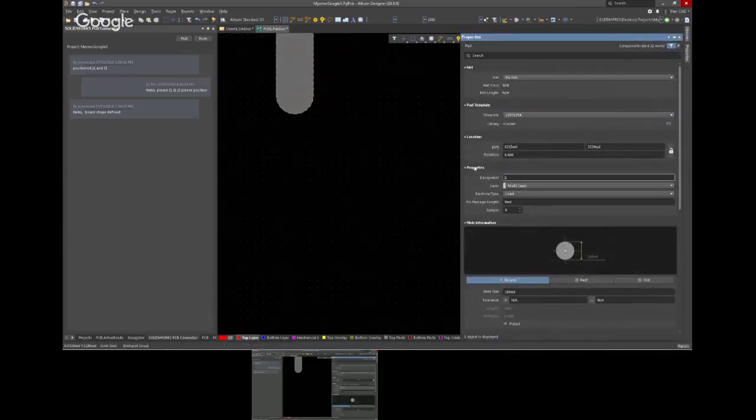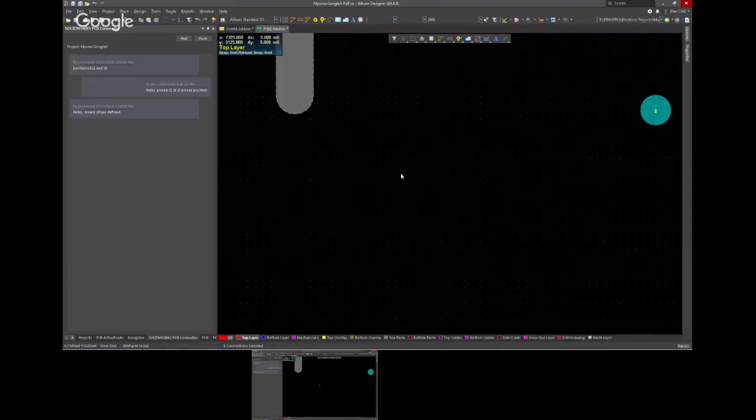So on the SolidWorks side, can you see the traces? Not today, not through the connector yet, because this is something that we're considering in 2019, for two reasons. The way it brings it in really bogs down SolidWorks Mechanical, and it comes in as a lump. The way we resolve it today is we export the Parasolid from Altium, by layer or the entire copper, and superimpose it over the assembly in SolidWorks Mechanical. I can show you that one. So that's how we resolve it.